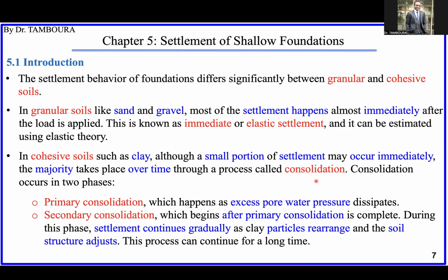That will make some movement in the soil particles, and they will do some rearrangement, and that will make some consolidation. This means the soil structure will adjust because the soil feels the load after the water is gone. That is secondary consolidation, after primary consolidation.